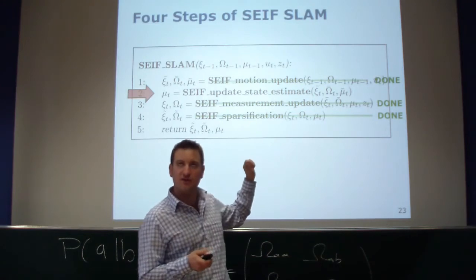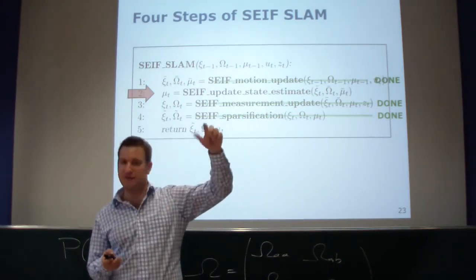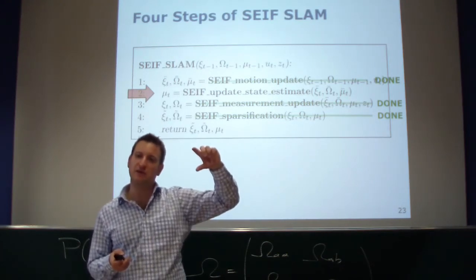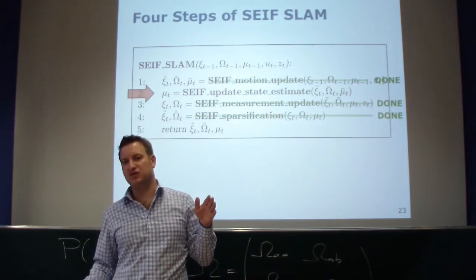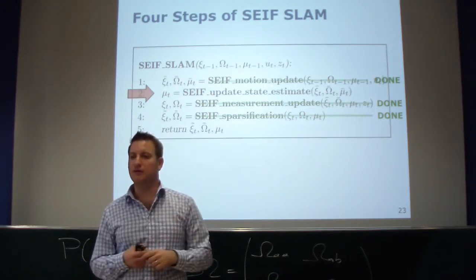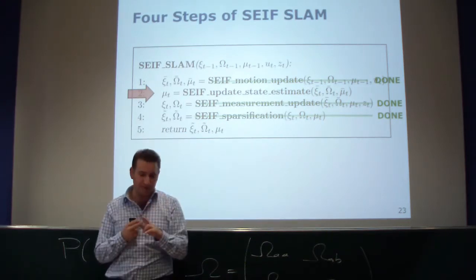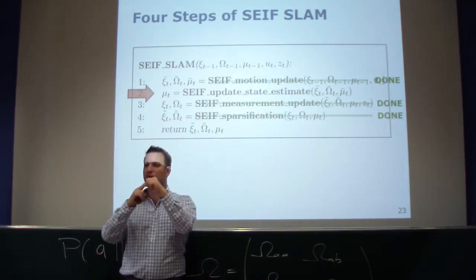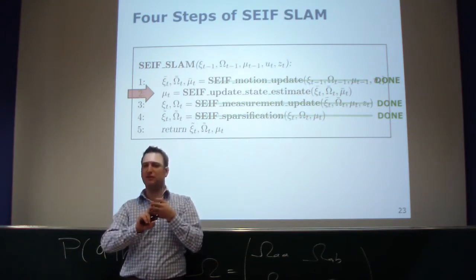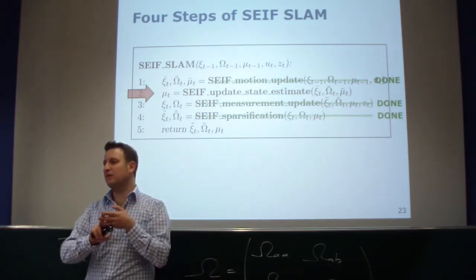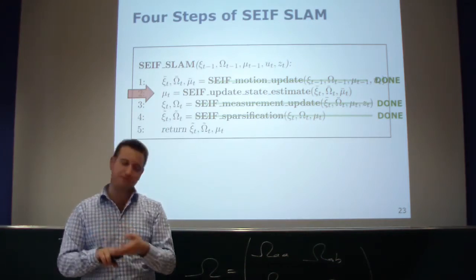These are those which are changed, especially both elements between the active features, the currently active features, and the active feature which becomes passive. All the landmarks involved in that, for them I need the mean. For the rest, the information matrix doesn't change, so therefore I need it for this update here. So I need the mean estimate for the robot's pose, for the active features, and the active ones which become passive. So m plus, m0, and xt. For those, I need the mean estimate for these computations here.